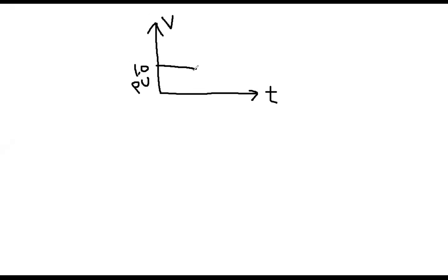Now, suddenly at this point, at t on time, for example, the fault happened. So therefore, there will be voltage drop. So it will be the situation in case of the induction machine, because that is the three-phase to ground fault example. It will be the nature, because you see it does not have any AVR and governor. So it is not like that it will come back and it will settle down. So in most cases, it does not come back because it does not have any control means,